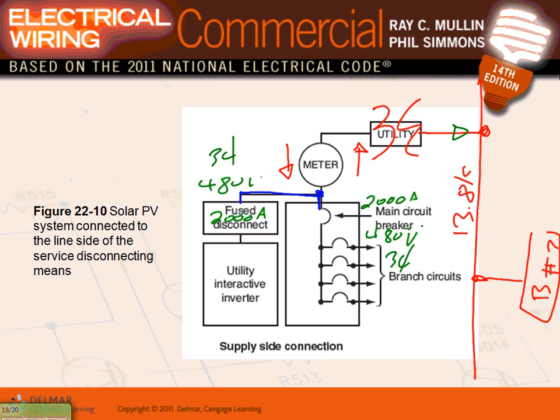So now if my building is consuming 2000 amp, all the power that I generate will be consumed by my building. At one time, because I sent my employees home, we're not working, my load in my building went down to 1000 amps, right? But I'm still generating 2000 amps. The other 1000 amps will go right through here, through the grid, and tie into my neighbor. I'm giving my neighbor a chunk of power, and I am being credited for it. I'm generating power and sending it to the grid.